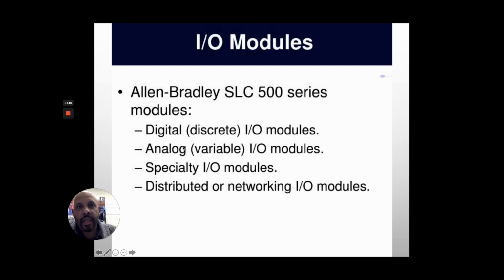Analog is when you're sending a signal to an output, let's say 4 to 20 milliamps, but don't get that technical yet. If you want something that goes from 0 to 100%, it's not the same as opening a valve that is just on or off, open or closed. You can open a valve slowly and control it: I'm opening this 10%, 20%, 50%, 100% full open. The same with analog input. With analog input, you can have a level in a tank. Is the level of the tank completely 0 at the bottom? Is it all the way at the top, which is 100%?